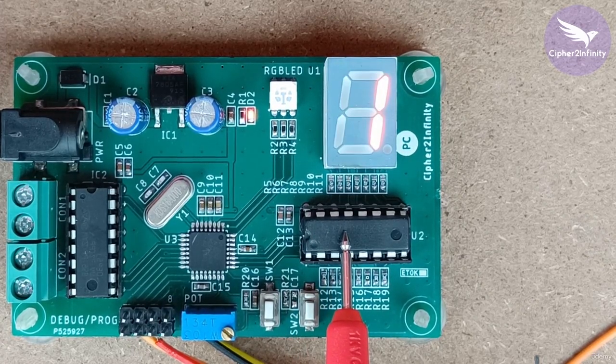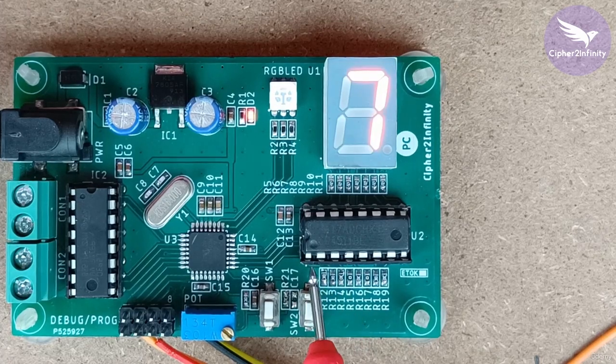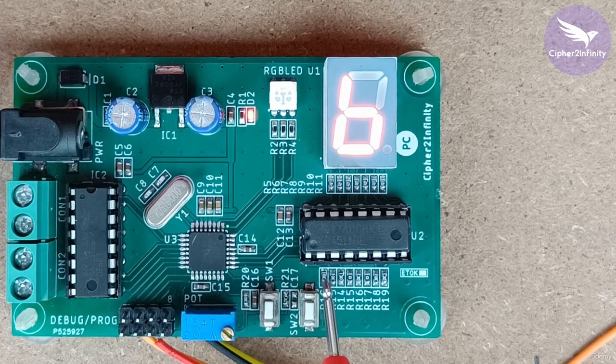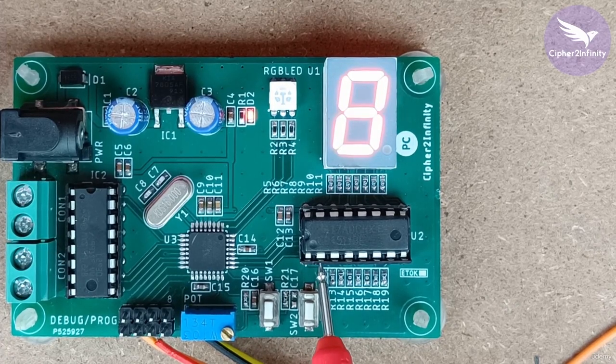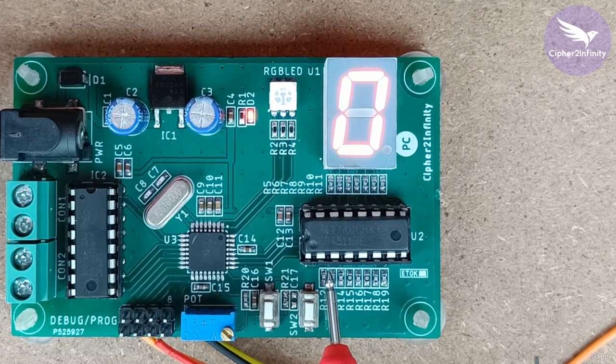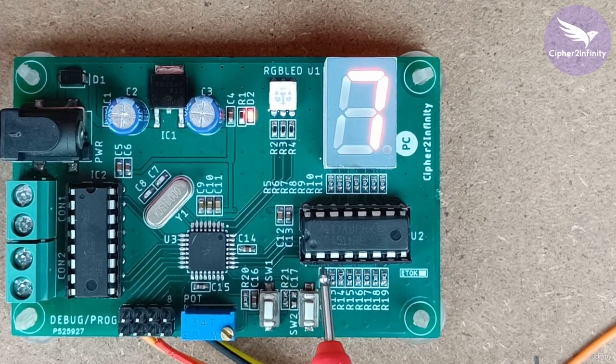Then the second mistake is, while soldering this IC base, it might happen that the IC base itself is soldered in the wrong orientation, okay? So you have to be conscious while soldering the IC base on the PCB, because once you solder the IC base in the wrong orientation, removing this IC base from the PCB is going to be very difficult. Until and unless you have a hot air gun, it will be very difficult to remove the IC base from the PCB.